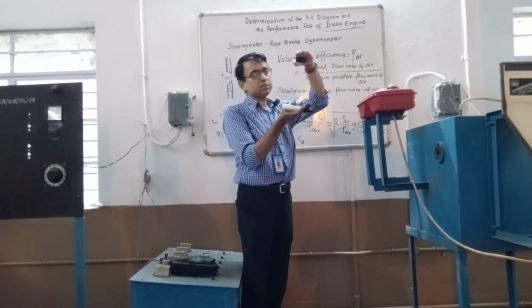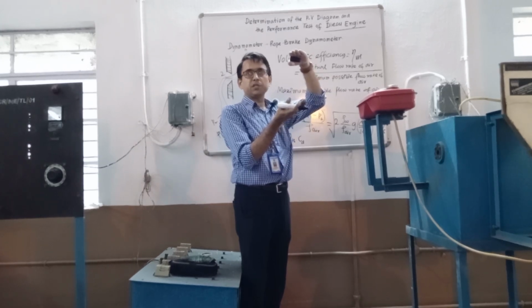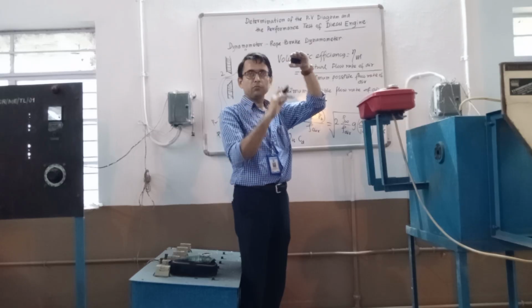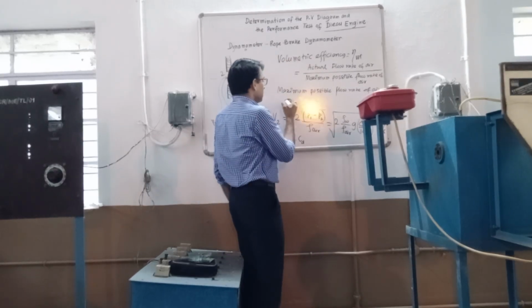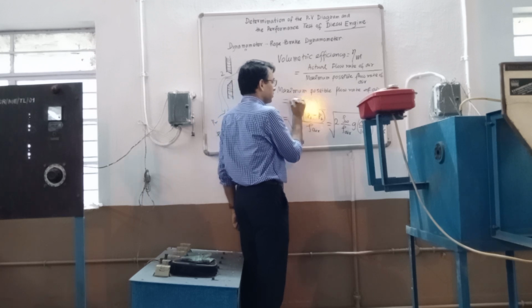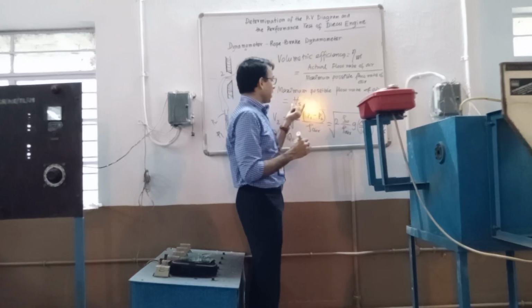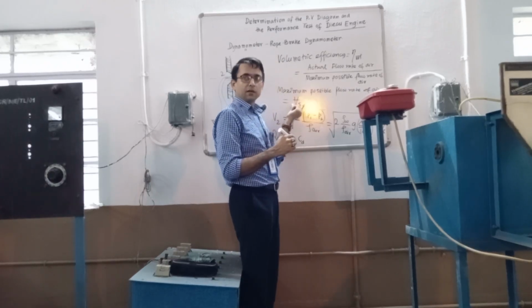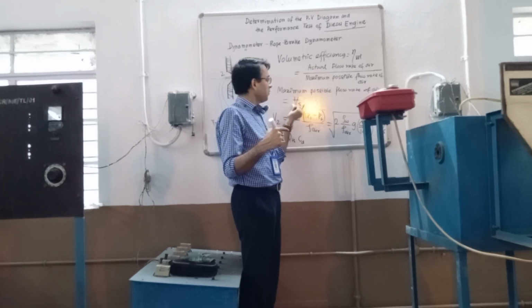Swept volume means the volume swept by the piston between TDC and BDC. So that is the maximum volume the engine can inhale, right? Swept volume is the maximum volume. So this is per cycle. In one cycle, the engine can inhale maximum, that is Vs, swept volume.